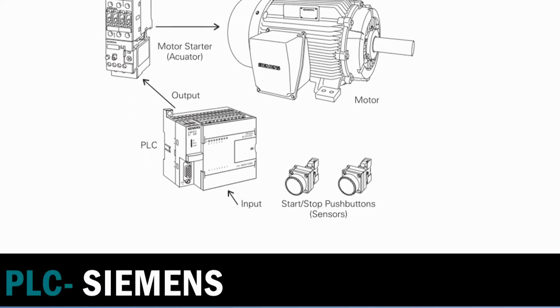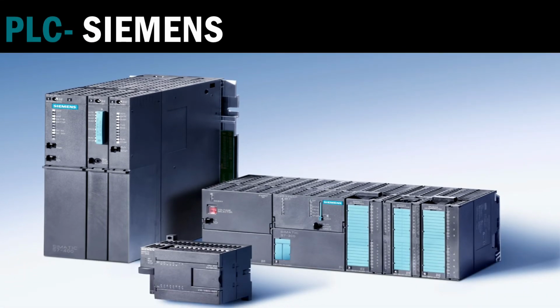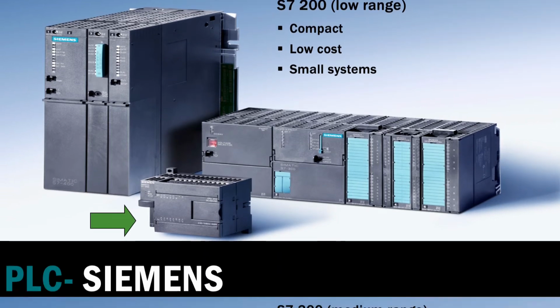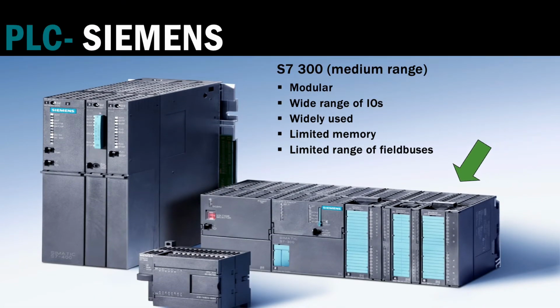Now we will see the different ranges of Siemens PLCs. First, the low range PLC in Siemens is the S7-200. This is a compact PLC and low cost. This PLC is used in small systems. Compact means a limited number of IOs and memory. If you go for the medium range, it is the S7-300 series. S7-300 is a modular PLC with a wide range of IOs. That means we have a number of IO expansions in the rack, but there is limited memory and a limited range of field buses.